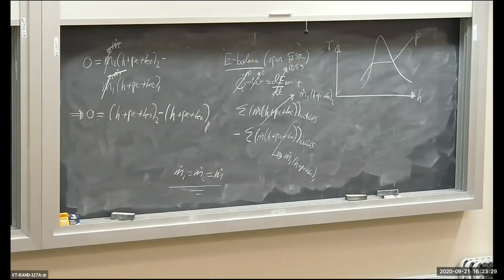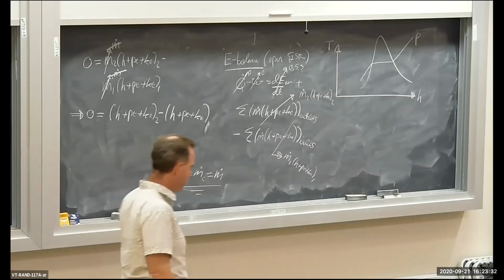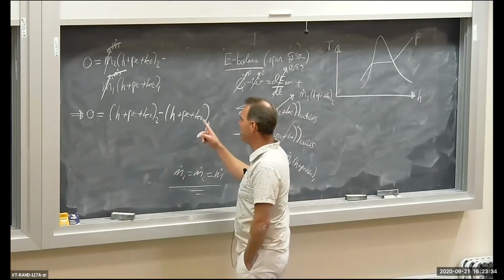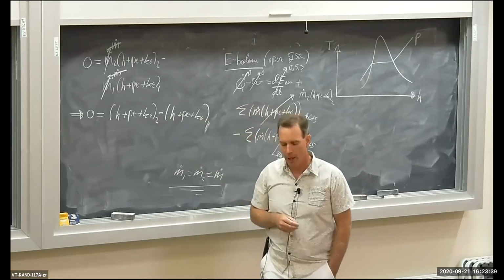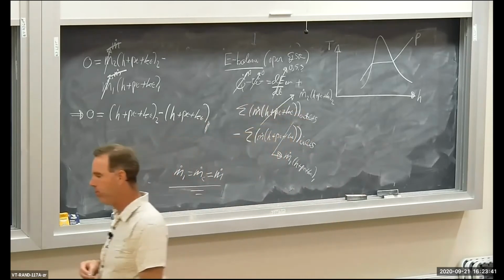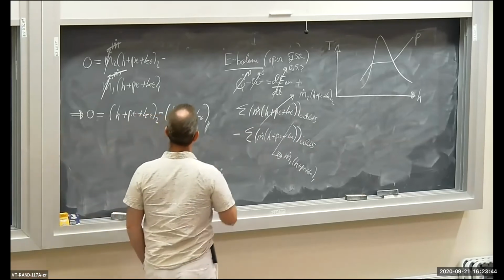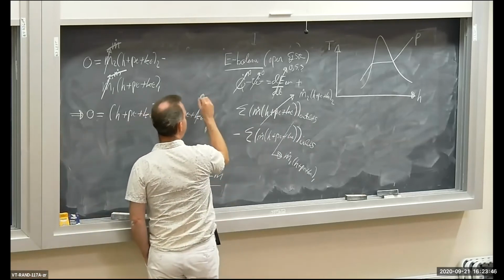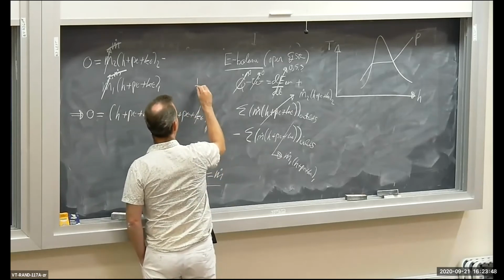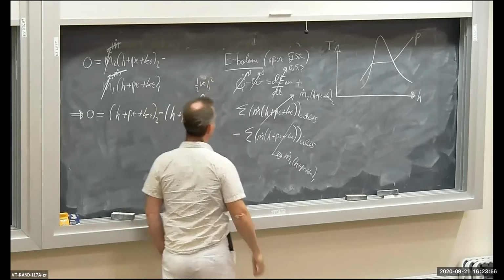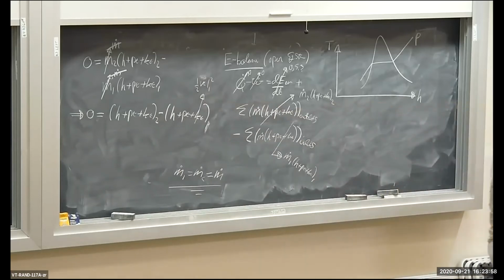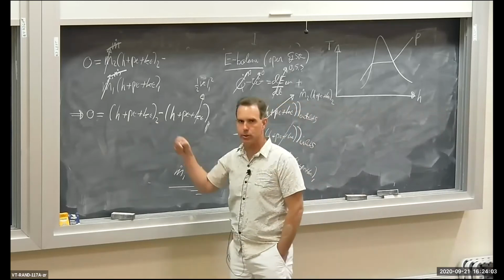Can we get rid of anything else? These kinetic and potential energy terms. The kinetic energy terms at the inlet and the outlet, that's specific kinetic energy. Those have to do with the average flow velocity. So like this guy here, KE at the inlet, this is going to be 1/2 times an average velocity at the inlet squared. And on the outlet, it's going to be 1/2 velocity at the outlet squared.